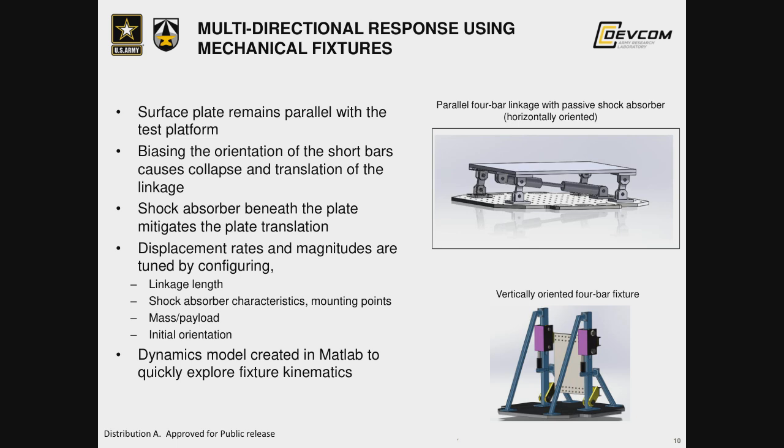This may be useful in the testing of floor-mounted seats, in which the insults measured in the transverse direction really can't be ignored. Similarly, where seats may be wall-mounted, this 4-bar linkage system can be repositioned. Essentially, it's been rotated 90 degrees, and a wall-mounted seat could be attached to it to produce the inward-outward motion of the hull wall.